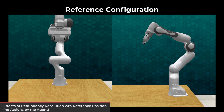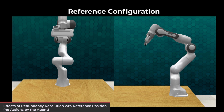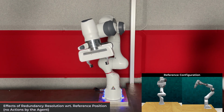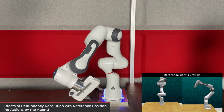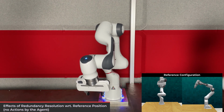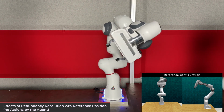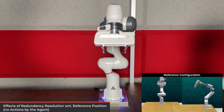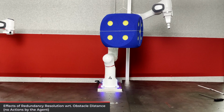Let's take a look at the effects of redundancy resolution, that is, only q̇_0. Here, we would like to minimize the distance between an initial skewed configuration and a reference configuration. You can observe that q̇_0 does not have any effect on the end effector position. As can be seen, we can use a reference configuration to push the robot towards a more upright configuration. Here's the influence of redundancy resolution when maximizing the distance between the robot links and an obstacle, here the cube.